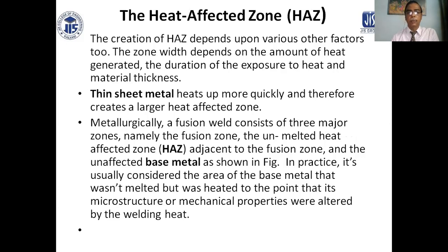Heat affected zone: the creation of the HAZ depends upon various other factors too. The zone width depends on the amount of heat generated, the duration of exposure to heat, and material thickness. Thin sheet metal heats up more quickly and therefore creates a larger heat affected zone.